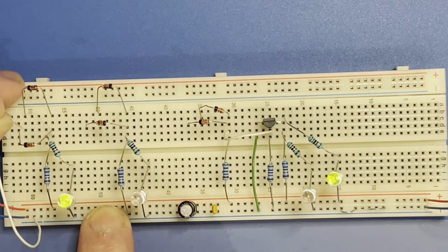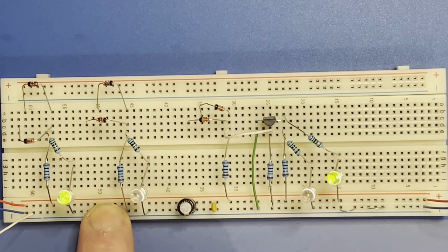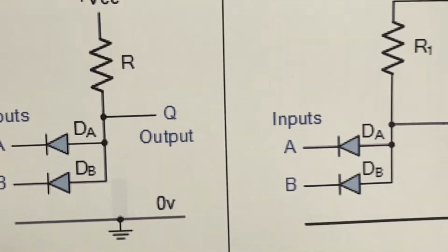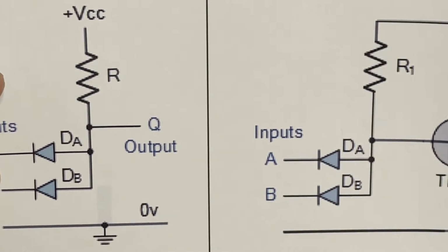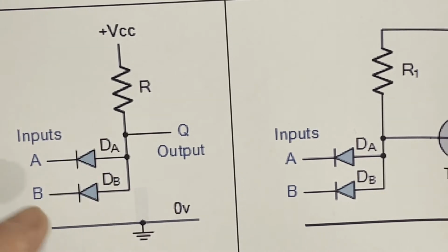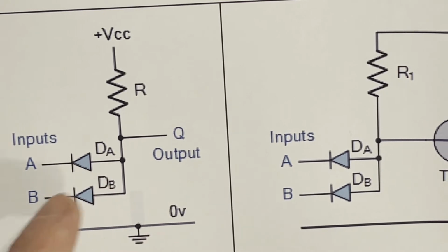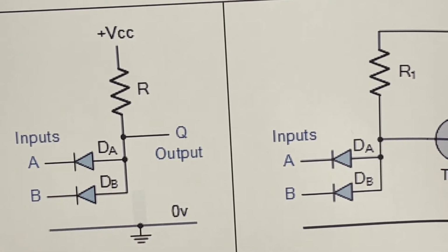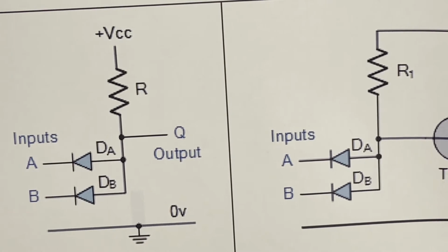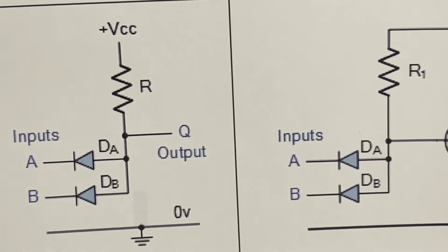But the problem is, you can't cascade it. You can't just keep linking these together as you can a true logic building block type gate. As the diodes drop 0.6 to 0.7 volt typically, as you try and cascade the thing, the output voltage will change. If you're only cascading AND gates in the same direction, the output will be 0.6 higher than the input at each stage. So you go through 5 gates and you've got about 3 volts difference in levels. So you get to a very, very fuzzy and confusing state as to what level it's at.